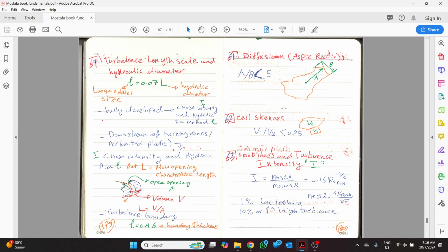This is why you're constructing a cell. If you find something like this, you need to refine the cells, make cell sizing, adaptation, etc.